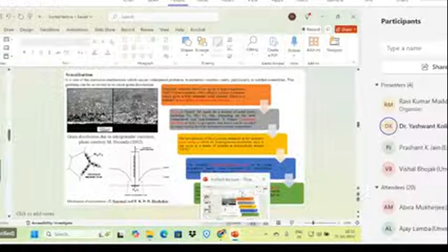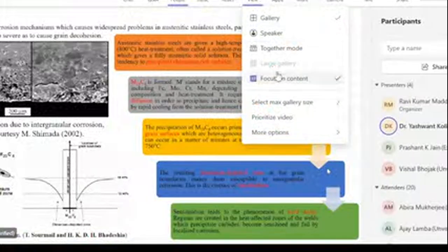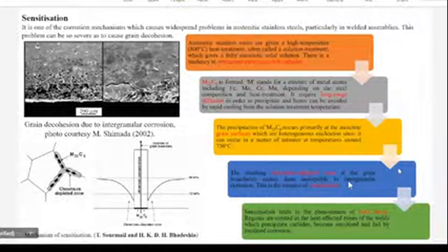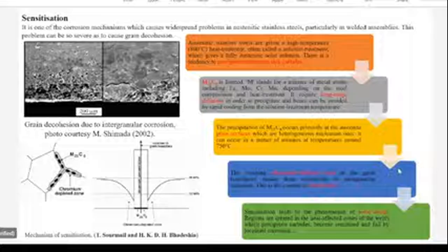And other factors are also there, like shielding gases and wire movement. But the main dominant factor for lateral deposition is this voltage control. So if we can reduce the voltage by 1 or 2, then we can control that lateral deposition. So I hope you have got the answer.